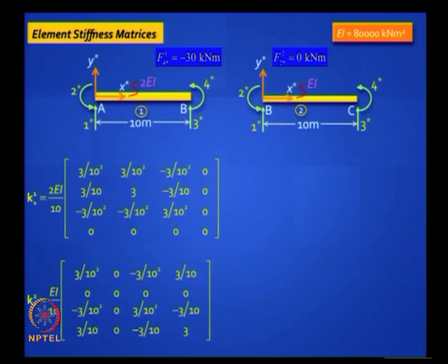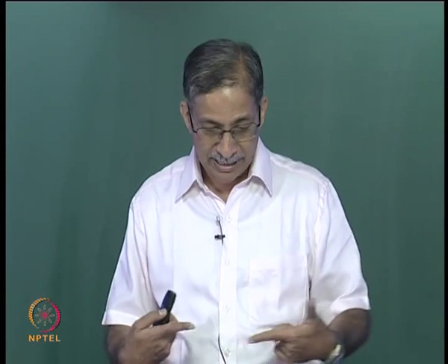This part you can generate, remember those formulas which we generated for the two elements. Can you generate the element stiffness matrices? Then can you multiply them with the identity matrices and put the linking coordinates, and you assemble the structure stiffness matrices, you will get lots of zeros. The second row and second column are dangerously zero, but do not worry, they do not belong to the active degree of freedom, so let them hang around there.